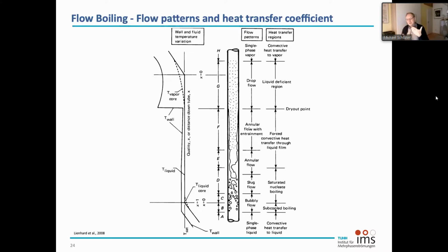And what now happens is, because there is no latent heat anymore left for the evaporation, the temperature of the wall suddenly increases. And this is our dry out point again. Yeah, the same what we have discussed before on this metal wire. Here we have this now at the pipe, and it's the same situation. Yeah, and here you see that we have this strong dry out.